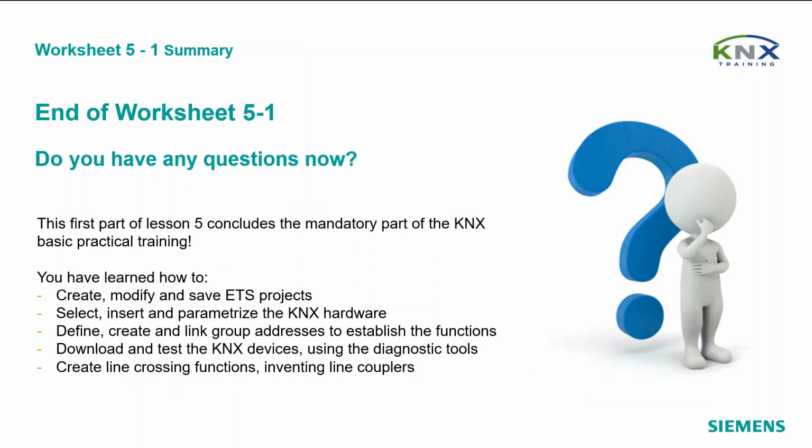You have learned how to create, modify and save ETS projects. Select, insert and parameterize the KNX hardware. Define, create and link group addresses to establish the functions. Download and test the KNX devices using the diagnostic tools. Create line crossing functions, involving line couplers.